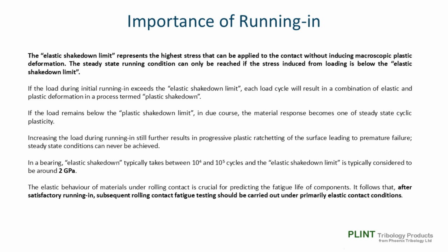The elastic behavior of materials under rolling contact is crucial to predicting the fatigue life of components. It follows that after satisfactory running in, subsequent rolling contact fatigue tests should be carried out under primarily elastic contact conditions.